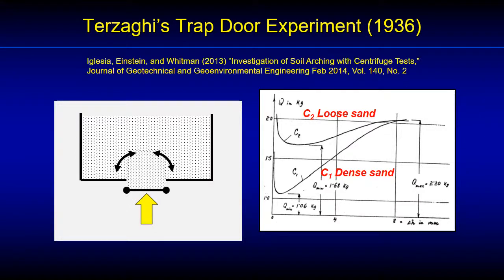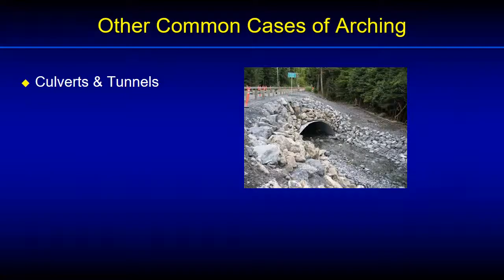Subsequently, there's been a lot of interest in this subject, and additional research, such as that recently described from centrifuge experiments by Iglesias et al. in the journals, has confirmed the general understanding of arching first described by Karl Terzaghi. This concept has broad application in civil engineering, particularly with respect to the design of culverts and tunnel support structures.